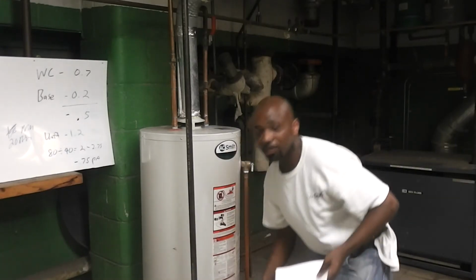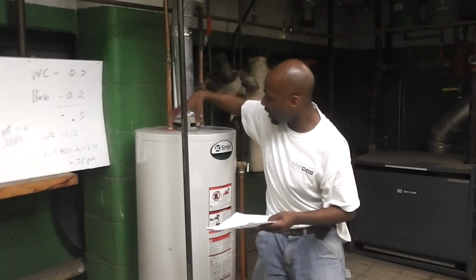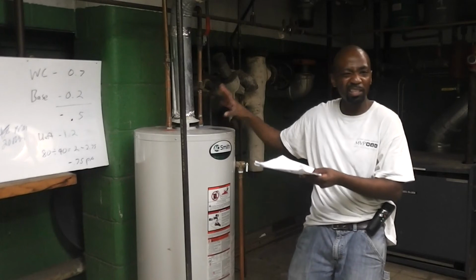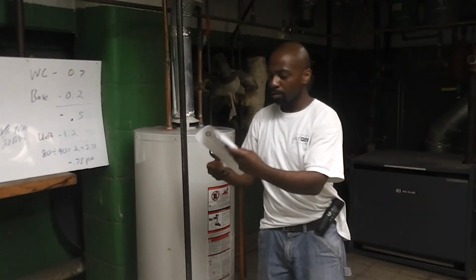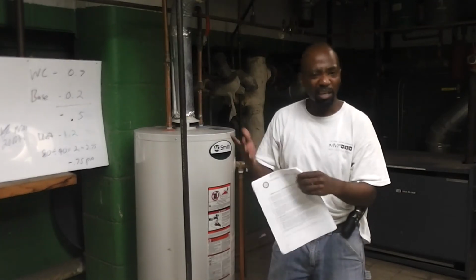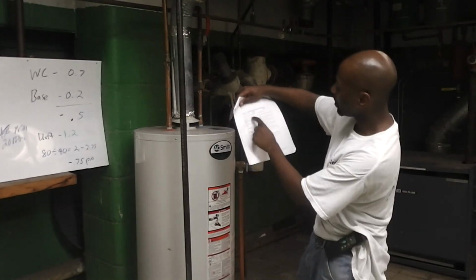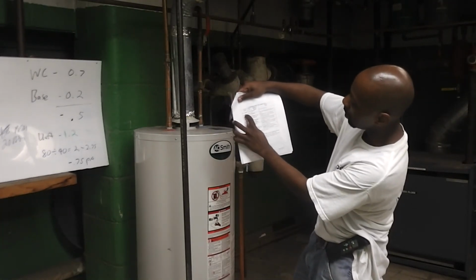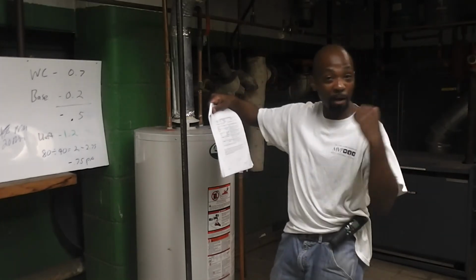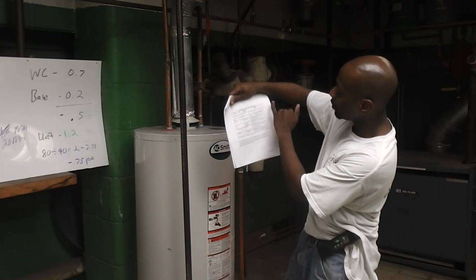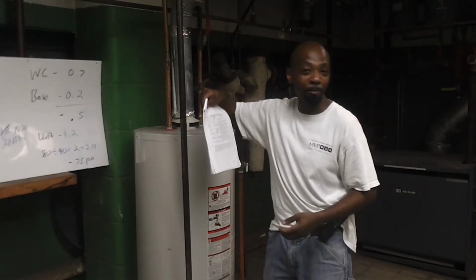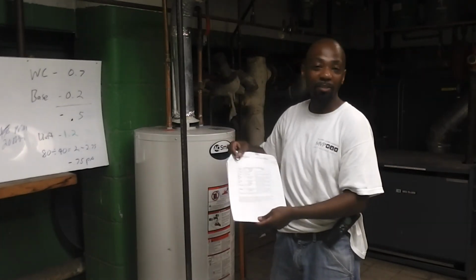So what does that mean? Well, so far it's pretty much the same thing as our DHW. That one had roughly 20, this one had 22. So if I refer to my action level to get a clear idea of what to do, I'm almost in the same spot, right? 0 to 25 ppm, that's what we got for our boiler. We passed spillage, we passed draft. So our retrofit action, we can still proceed with our work. We can still do what we've got to do.